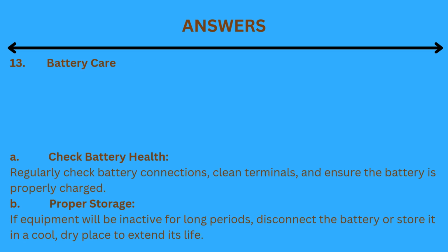13. Battery care. A. Check battery health. Regularly check battery connections, clean terminals, and ensure the battery is properly charged. B. Proper storage. If equipment will be inactive for long periods, disconnect the battery or store it in a cool, dry place to extend its life.